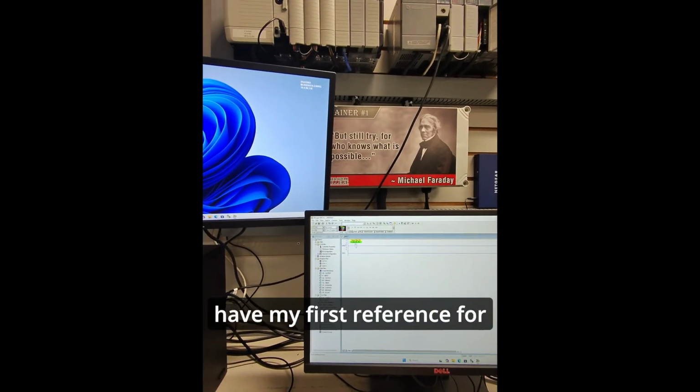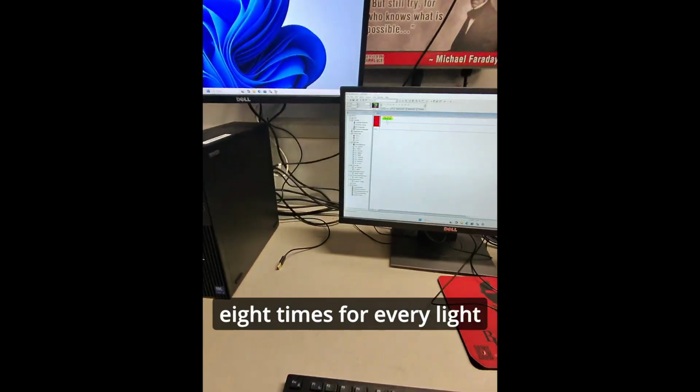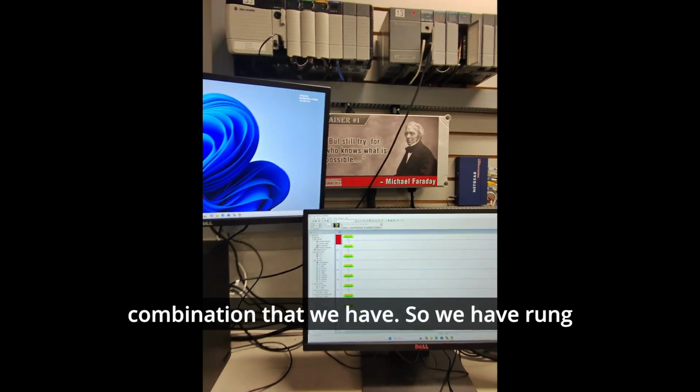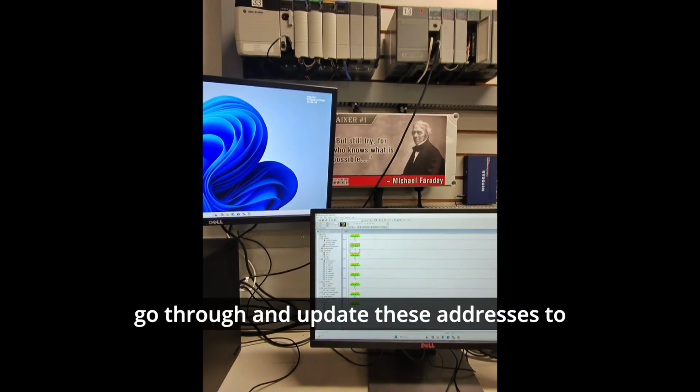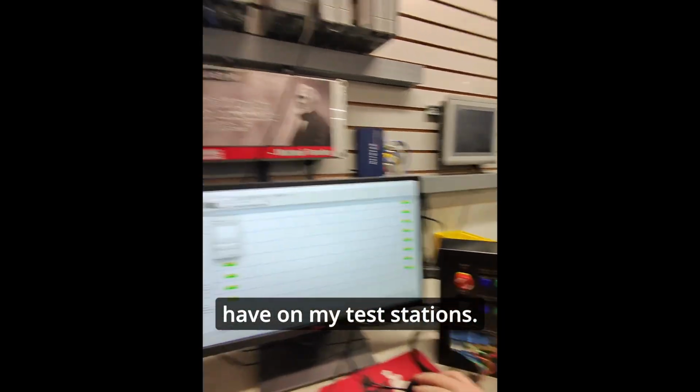Okay, so now that I have my first reference for my first input and first output, I'm going to just copy this 8 times for every light combination that we have. So we have rungs 0 through 7, 8 rungs, and I'm just going to go through and update these addresses to match the addresses that I have on my test stations.